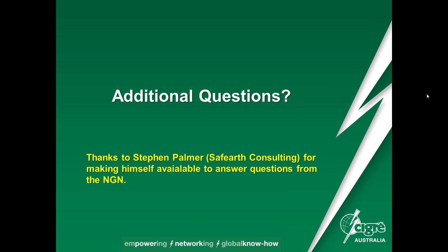Previously we've injection tested a substation. It was only just fractionally unsafe according to IEEE 80. And then reviewing it via EG0 guidelines, because we never had any proof that the substation was actually ever designed to IEEE 80 anyway, we've reviewed it with EG0 and said, well, actually, according to our standards, which we use now, which is the only standard it's ever been really, truly assessed to, it's safe. So we've gone, right, we don't have any issues with this. The contractor, go in there and build on it now. Have you ever seen conflicts with one company using IEEE 80 and another company using EG0 about which one is the one to be followed?